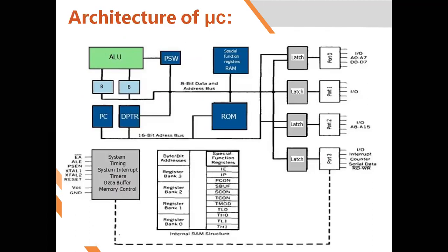If I tell you to perform addition of 8 plus 9, then 8 and 9 are the operands and plus is the operation. So in any arithmetic and logic operation, your first operand should be present in the accumulator, and the result of the operation is always stored into the accumulator.